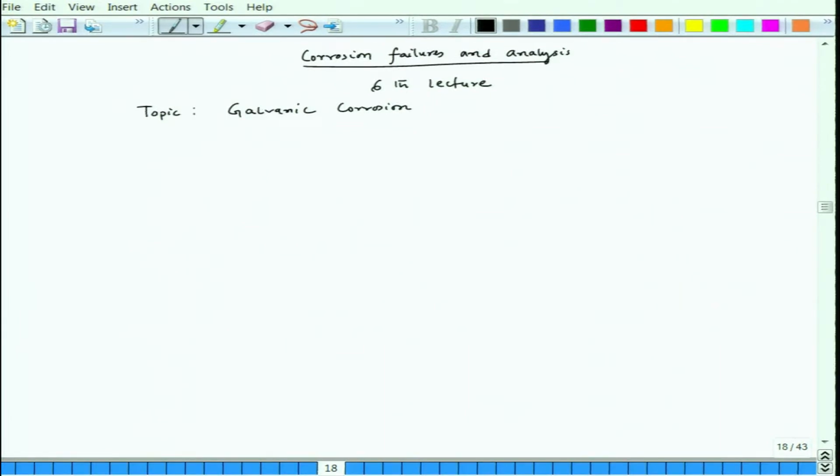It is not happening over the entire surface covered by the droplet. Okay. So, if you go back and see, this is the droplet, and the corrosion pattern is like this. In the center part we have the highest corrosion, and the center part is preferentially anode, and the periphery region is preferentially cathode.